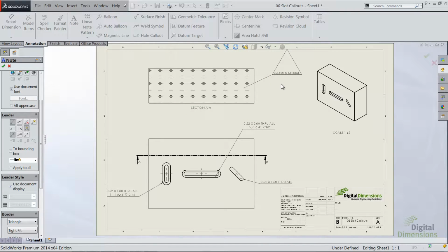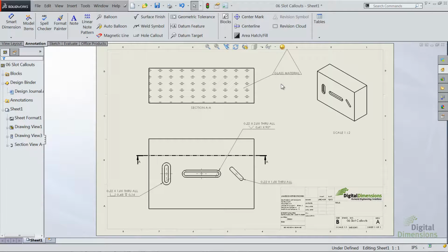The next enhancement to mention here is that if you've generated a part out of glass, as I have here, you'll note the new crosshatch style that's available in SOLIDWORKS 2014. So if you've ever generated parts out of glass and done a crosshatch on them, you may have realized that the default crosshatch pattern on it was fire brick.